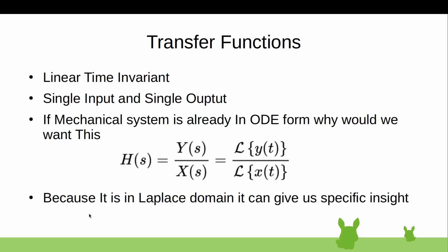So when you multiply something by s in the Laplace domain, in the time domain it is a derivative. So intuitively, what do you think x double dot as a function of time will be? Yes, it is s squared times x as a function of s. That's quite good.